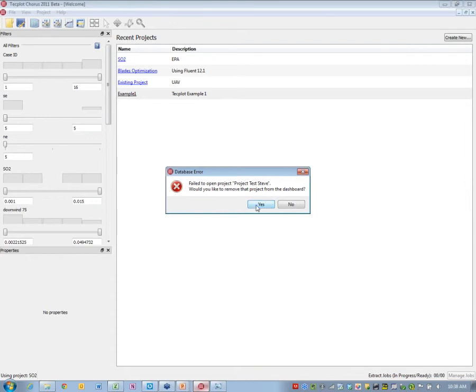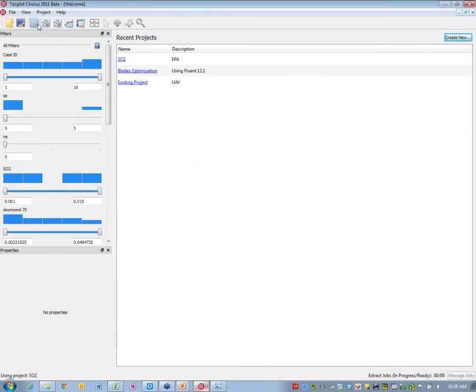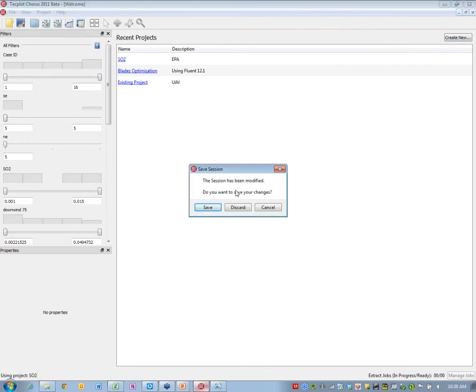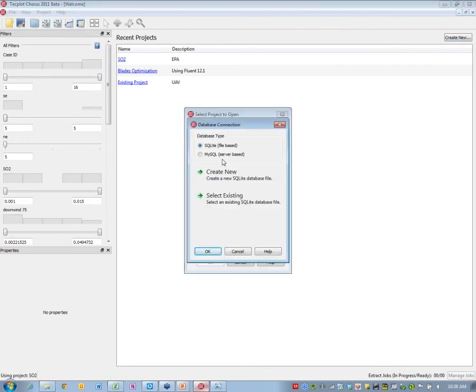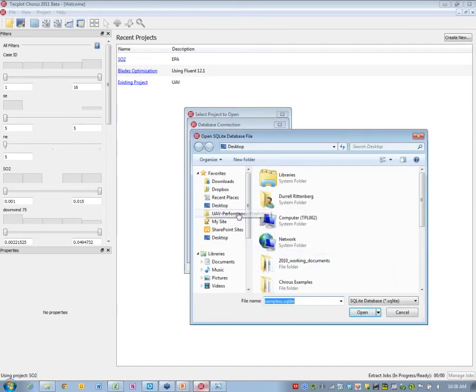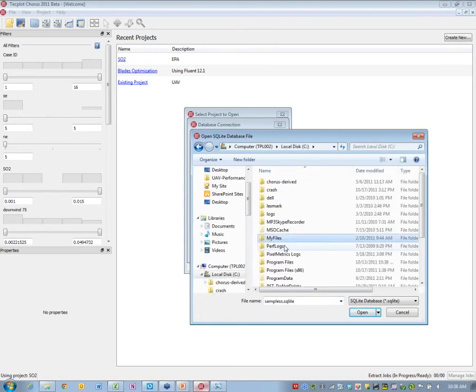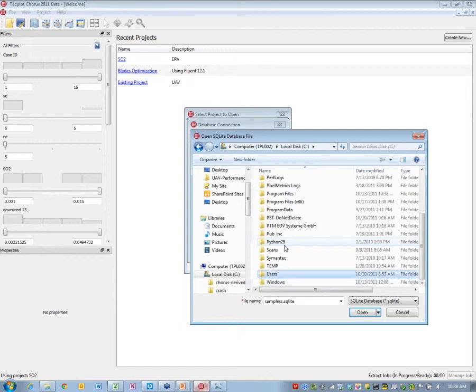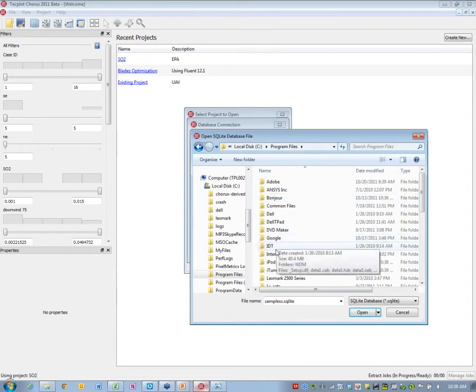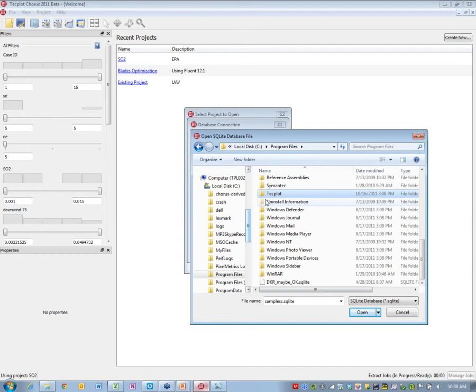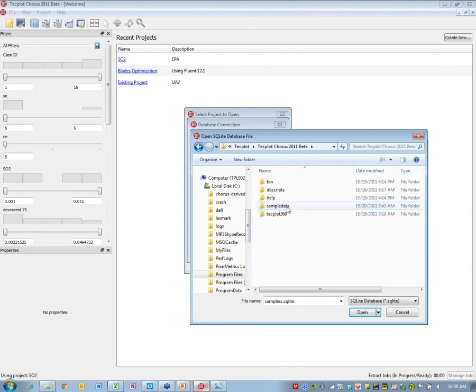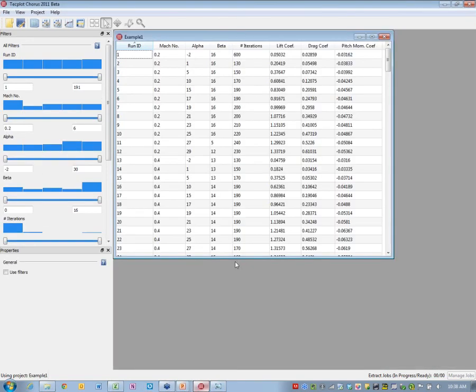But, you know, they're just to understand the performance of the aircraft, say from a flight mechanics standpoint, stability and control of the aircraft is one obvious use. Another would be for inputs into post-processing, like a flight simulator. You might want a simple surrogate model that could be used to provide your stability derivatives to the flight simulator for the dynamics analysis.